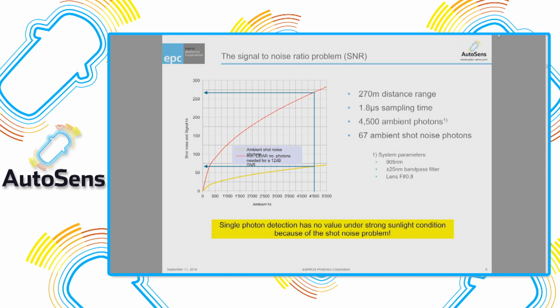So if you want to do a simple detection of a pulse, you typically need a higher amplitude of the pulse. Basically, let's say 3 or 4 times. So let's say 10 to 12 decibel, and then you are in a good domain. So looking at that diagram again,